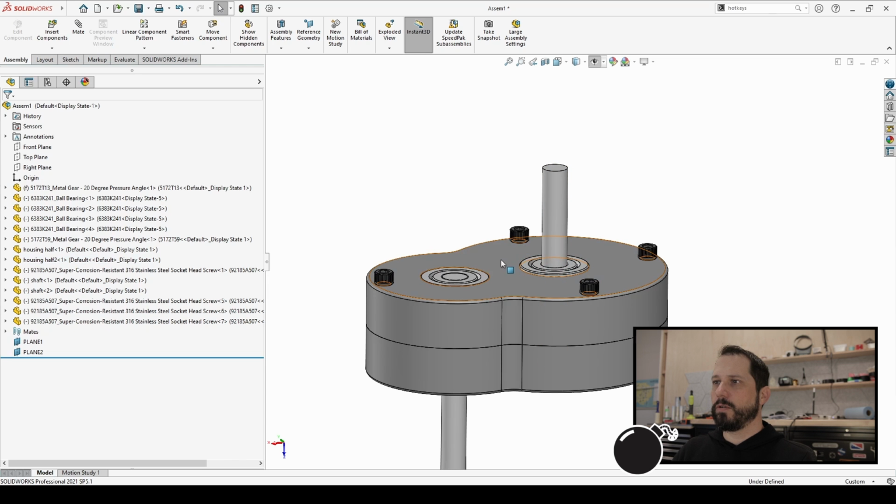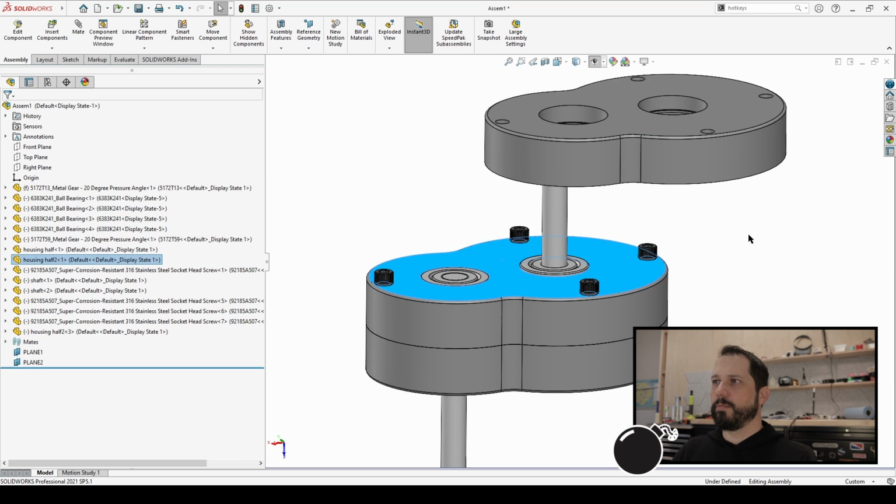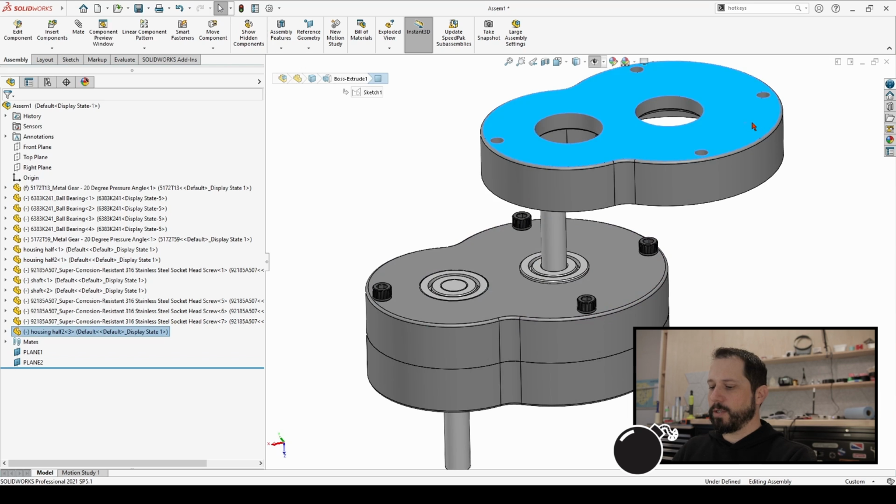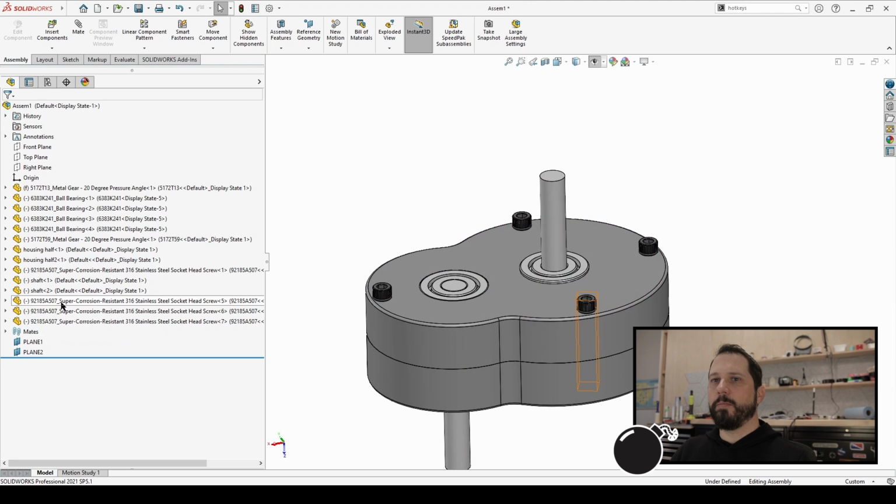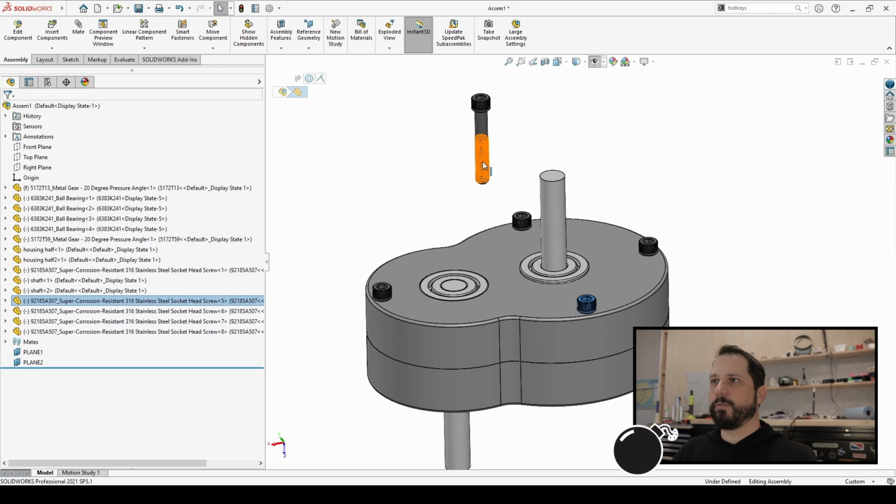In kind of the same way, you can actually just grab parts from your assembly. If I hold down Control, left click and drag, now I have another one of those parts. You can also grab from the feature tree over here. You can hold down Control, drag from there. Sometimes it'll get a little glitchy if you try to grab from the window, and it only works if you do it from the feature tree, but either way usually works.